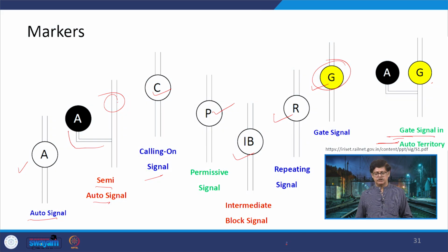So, with this we close our discussion now. Today we discussed about the various subsidiary signals which are used on Indian Railways. To name them like shunt signals, calling on signals, repeating signals, co-acting signals. And then we talked about the various indicators, the boards, terminators. They were related with points, speeds, shunting, stop, grid, etc. So, all of this information together, that makes the type of the signals which are provided on the Indian Railways.